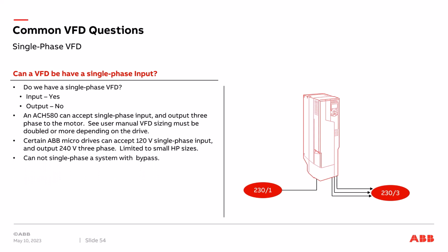We cannot single phase a system with bypass. The last thing you want to do is try to put a 3-phase motor across a single phase bypass. It will not be good and the results will not work out.